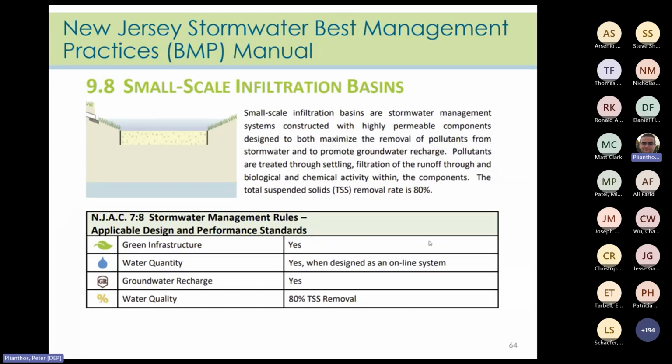The other tables below this first table, although not shown here, provide additional design criteria explained in the chapter. To reiterate, BMPs are awarded the TSS removal rate stated in the BMP manual only if they are designed in accordance with the BMP manual. That includes meeting the requirements for pre- and post-construction soil testing and a full maintenance plan, which Manesh will address next.